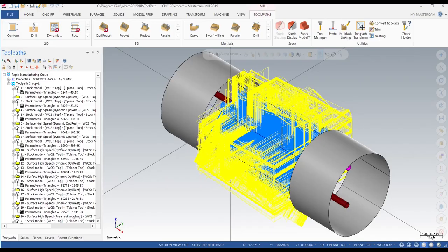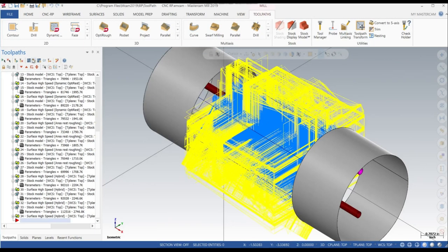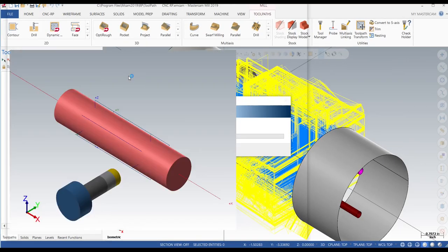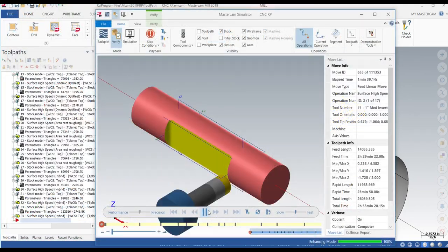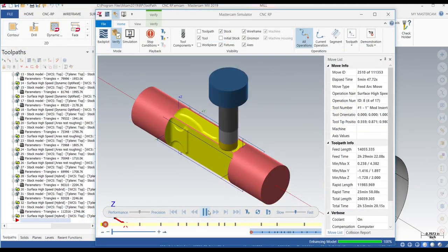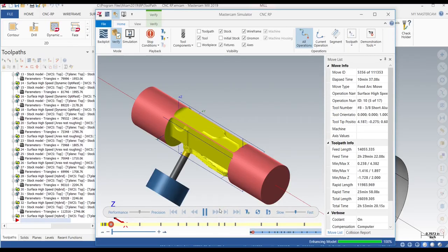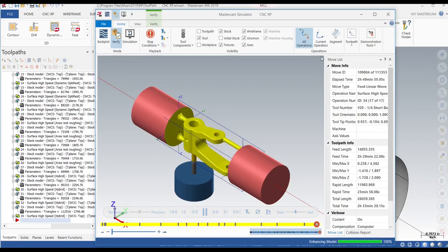This can be done pretty easily using Mastercam's Verify Simulation tool. To do this, first move over to this green play button and select all of the operations. Then move to this check mark and the Verify Selected Options button and click that. This will then start bringing up the simulation screen. I normally run the screen at max speed, but if you want a more accurate model, run the verification at a slower speed. After the simulation is done, you will see what the part should look like upon completion.